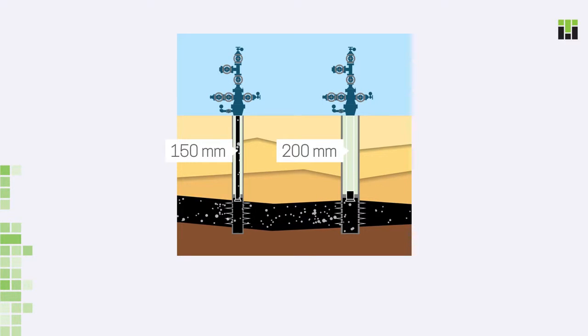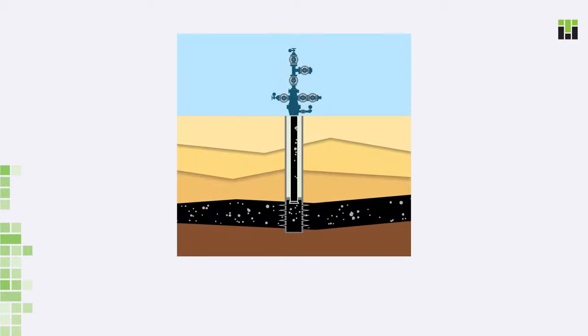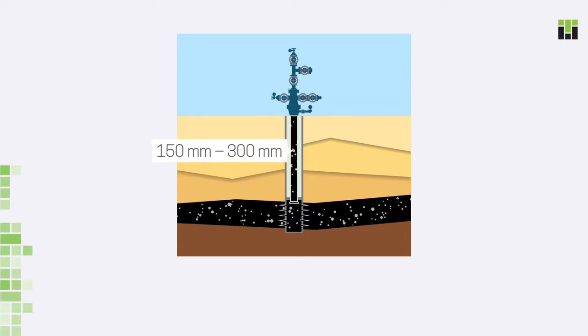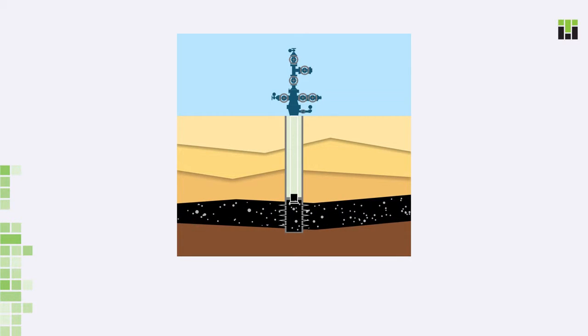And the bigger the production tube in diameter, the more gas is required to lift oil. There have been cases that large diameter wells, 150 to 300 mm, drilled into high-pressure, high-capacity reservoirs showed great production rates, but the open flow in such wells did not last long.